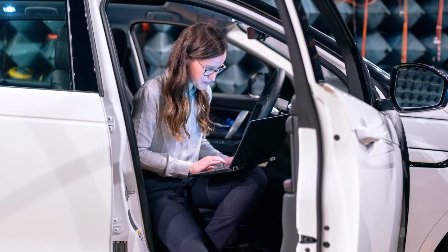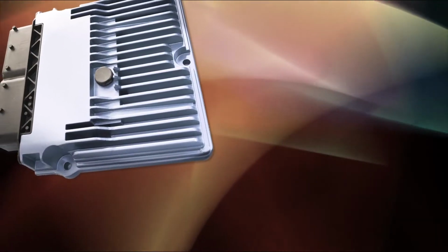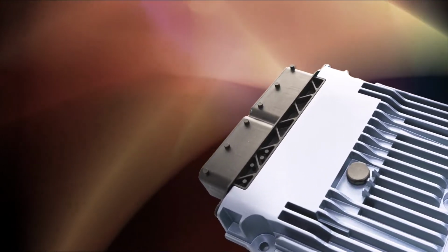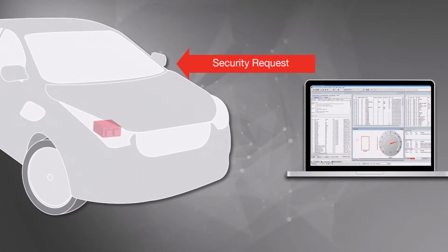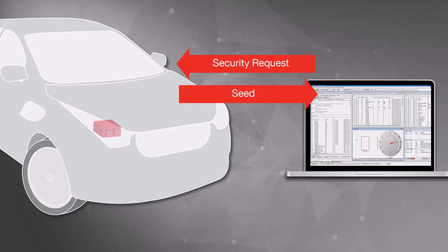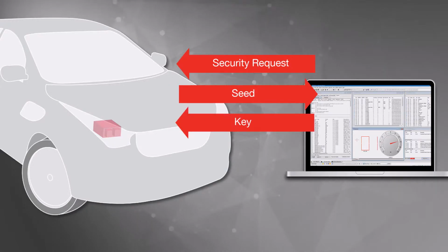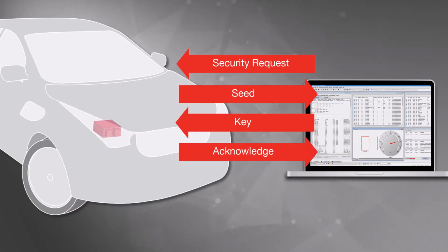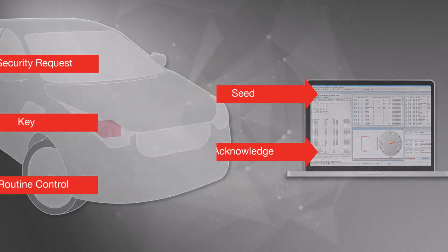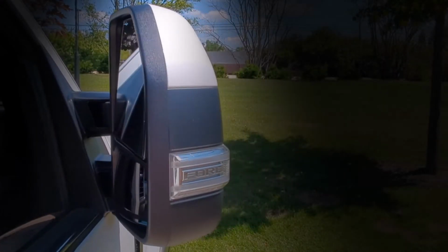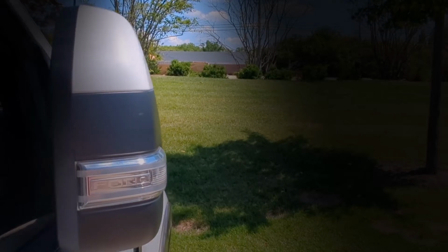During the development of EDT scripts, users will need to put the ECU into a different session or security level to run certain functions. One such example is running certain functionality through the routine control service. This service can be used to test vehicle functionality by triggering certain routines within the ECU. This could be anything from testing ADAS systems to ensuring relays are functioning correctly. This process is generally only accessible in the extended diagnostic session, and specific routines can be locked behind different security levels. In the following example, the routine control is being used to trigger the wing mirror test functionality.